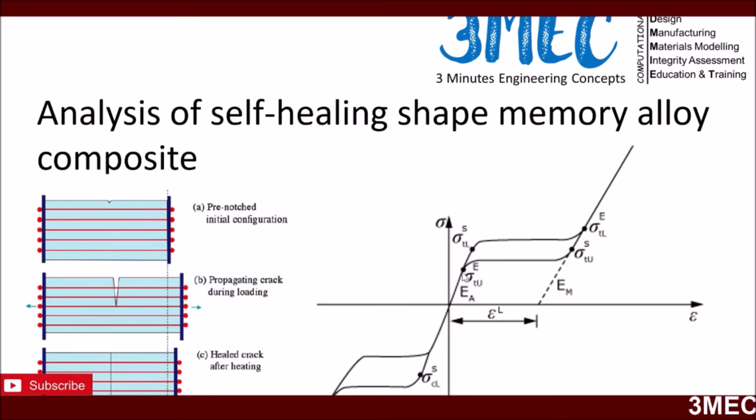And if you know the theory of shape memory alloys, they can have elastic deformation in the austenitic phase, and then they start to transform into the martensitic phase, and then they completely become martensite, and then everything is governed by that. Now if you unload the sample again, which is already transformed, then it retransforms back to the austenitic phase. So this is the martensitic phase, this area, and this is in between, and this is complete transformation back to the austenitic phase. And the same happens on the compression side as well.